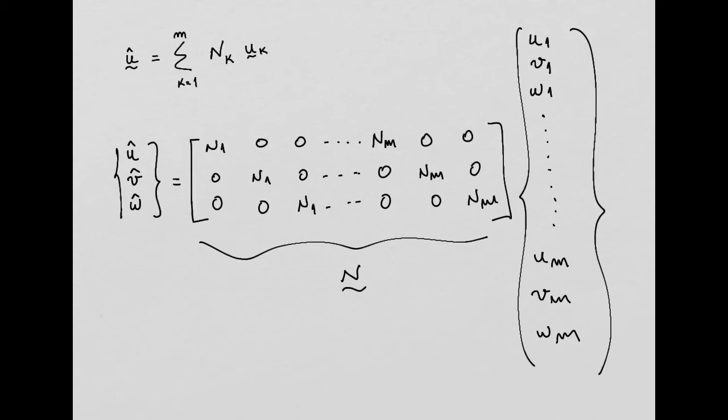Okay, so for example, if you are using a finite element with quadrilateral elements, a quadrilateral with 4 nodes, for example, plane stress and plane strain, you will have a matrix of shape functions. If you are using, for example, the same quadrilateral with 4 nodes, but for plate analysis, you will have a different matrix of shape functions.